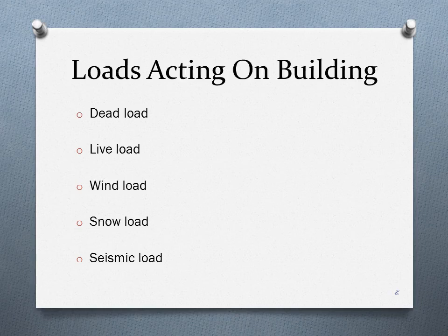First of all, we will see what we mean by load. Load means anything which exerts pressure on a structure. Whenever you construct any type of building, all these different types of loads will exert pressure on a structural component of a building. Here structural component means wall, column, slab, beam. Dead load, live load, wind load, snow load or seismic load will exert pressure on the structural component, and this structural component should be able to bear these different types of loads.